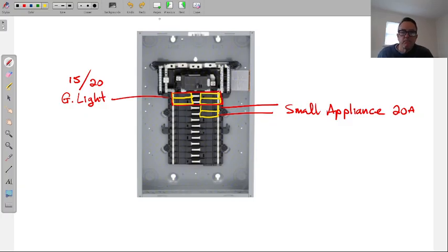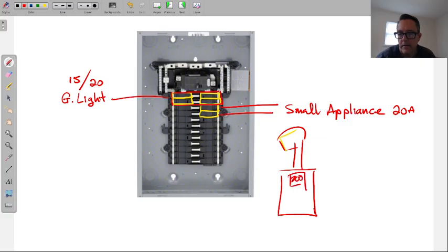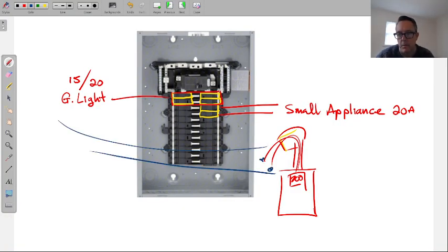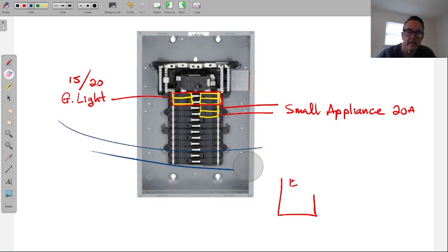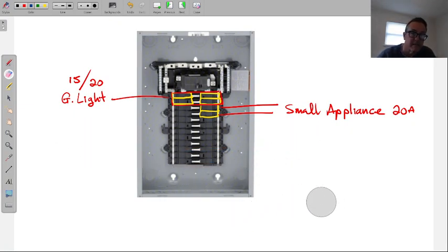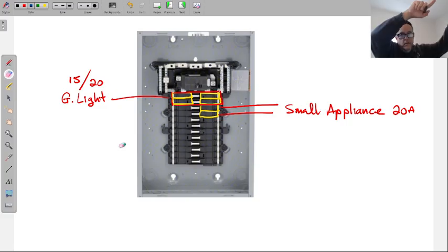But for like, if you have to dig out to the utility. Oh, no, we don't. Well, that's for residential. Usually, it's just the pole bringing the wires down. Right. So we don't do that far. We just set up the weatherhead. We just set up the new panel with the 200 amp main breaker. We set up the wires, and then the utility company brings their wires, and they are the ones that splice. Like all of Irvine is underground, and then. Oh, I see. Okay, so yeah, you would have to do the dig, but then again, you just run the wires over to the utility company, and they pick them up from there.